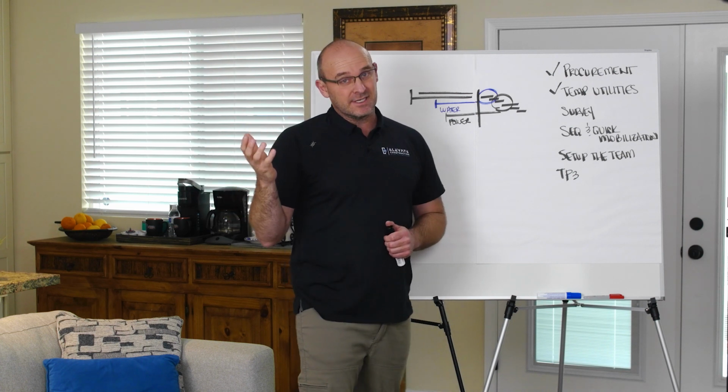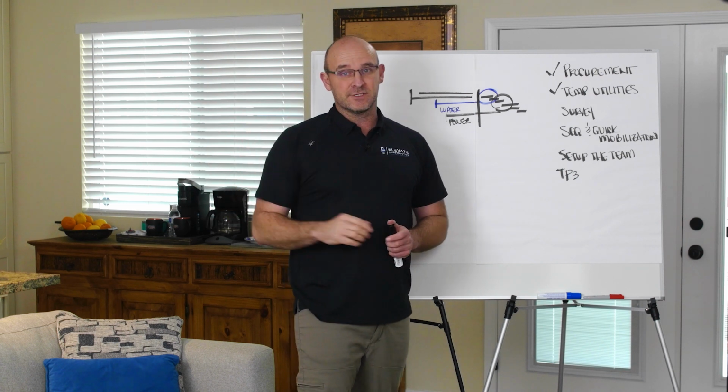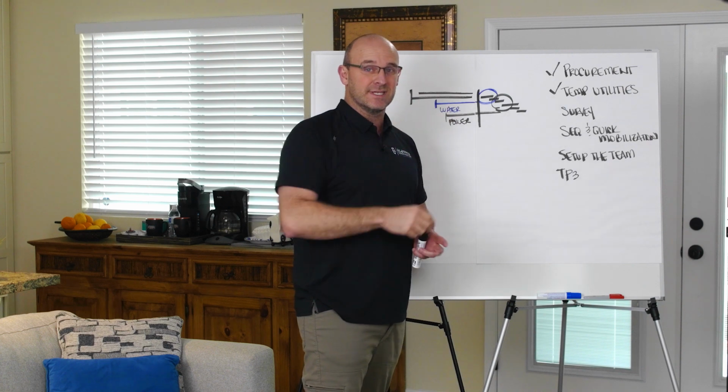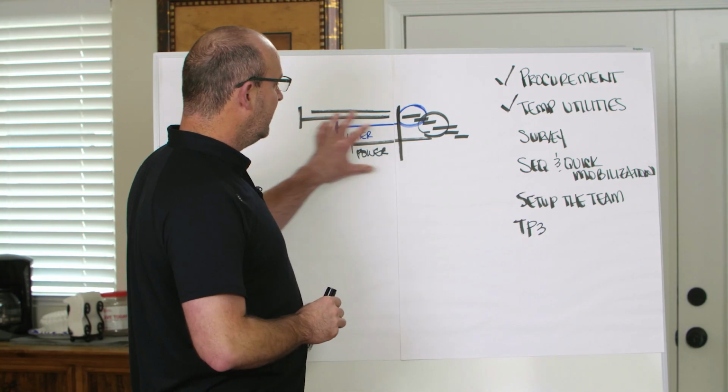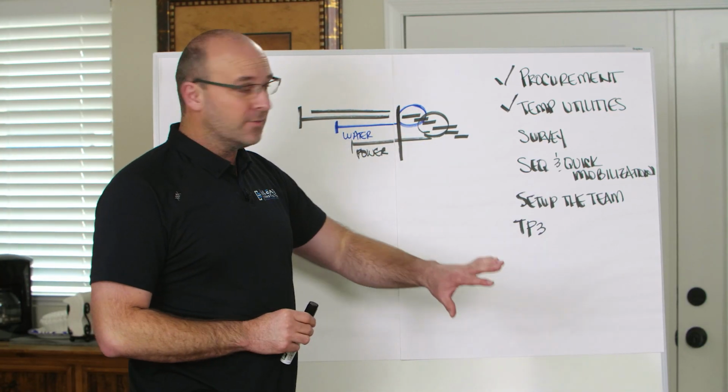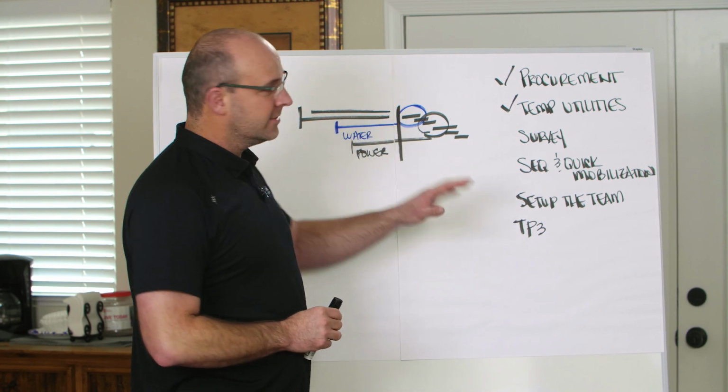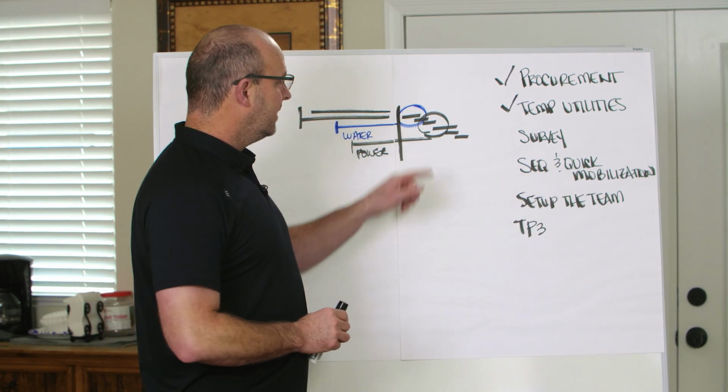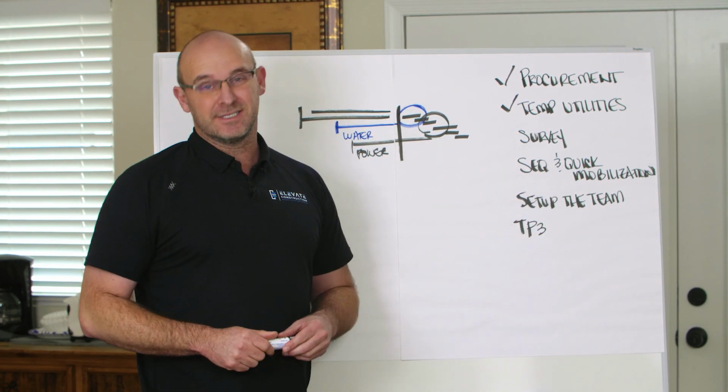I think it was by CenturyLink, and that took about 3 months to move out of the way. And if we hadn't seen those things, we would be in trouble. So make sure you get any permanent utilities out of your way and any temporary utilities to the project site by the time you need to start. Otherwise, it's going to be a big deal.